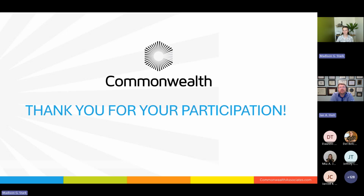Sure. Another thought that may be appropriate there is, whenever you get an X/R ratio of your system, whether it's at the utility or at your level, which may be in the medium and low voltage areas that you're studying, if you start getting above an X/R ratio of 17 per IEEE, you have to start thinking about the decrement of how your short circuit will decay. It'll decay slower at higher X/R ratios. So this goes to Madison's point exactly: if you have an interrupting rating of a value and a momentary rating of a value, you'll be a lot closer to the momentary value than the interrupting rating in that case.